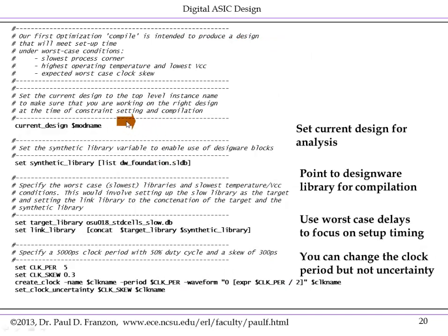We then set current_design to be mod_name. What we're doing here is starting at the top of the hierarchy. When you have a hierarchical design, this greatly simplifies the synthesis flow. Unfortunately, the Synopsys tool does not analyze the design to work out the hierarchy. If you don't do this, it'll start with whatever the last module that was read in was.